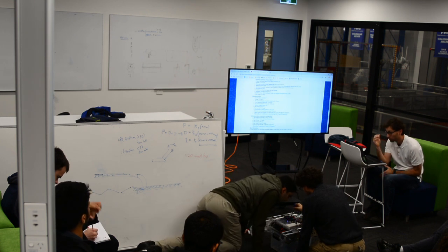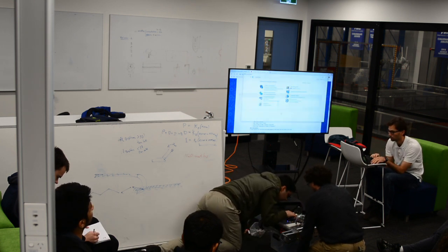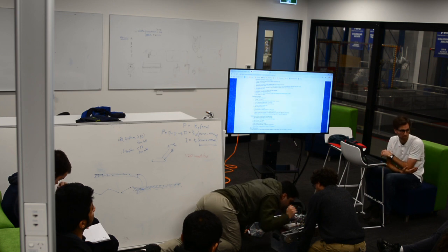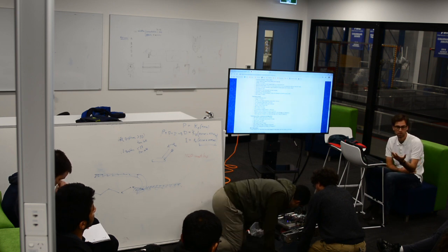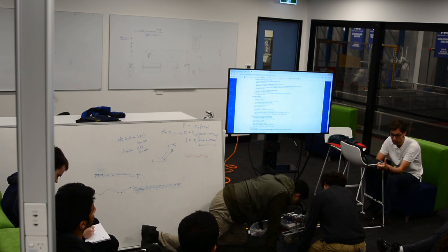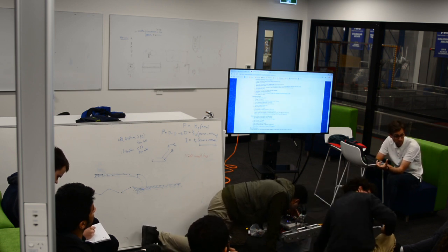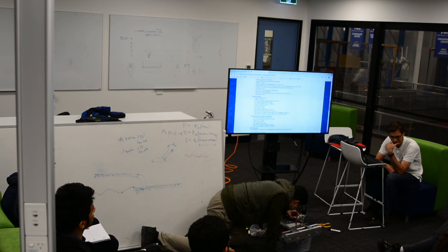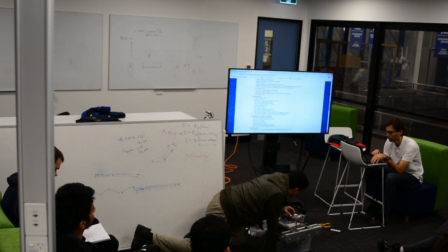So we could set our, and they're 4-inch wheels, so we could do some calculations to figure out if we want to do exactly a meter, how many pulses we'd need. That 4-inch wheel is about 10 centimeters, so a meter is 10 rotations. So we'd want 2,800 pulses to go one meter, I think. Although, no, we were doing more than that, weren't we? We were doing about a meter and a bit.